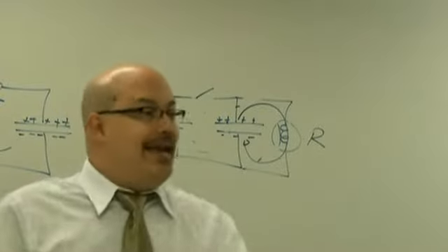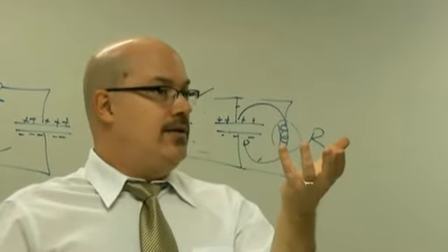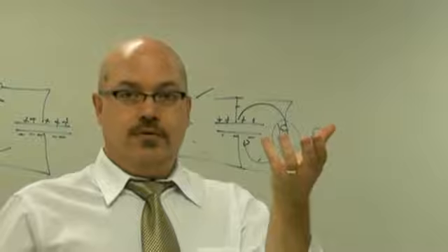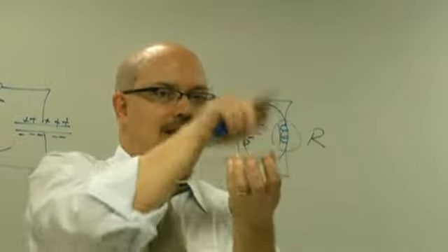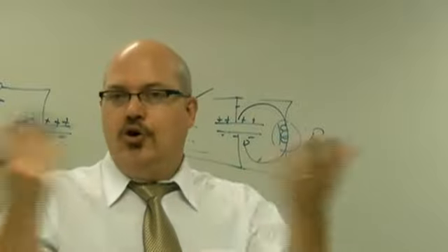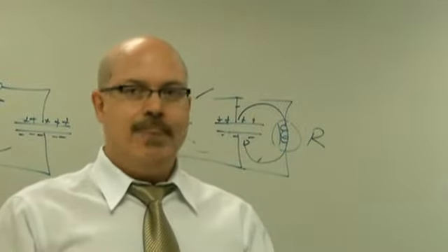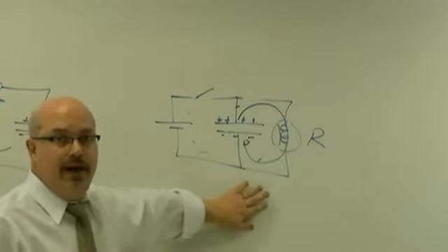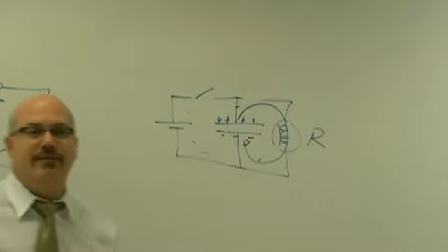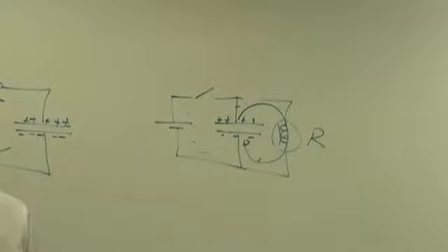And so the bulb will stay lit until the capacitor reaches equilibrium. The charge is going to come off and eventually discharge the capacitor, and there's no more stored charge, right? So it'll slowly die out. So that's one way you could design it so you open the door, the light goes on, close the door, and the light slowly goes off. Okay? That's pretty cool.